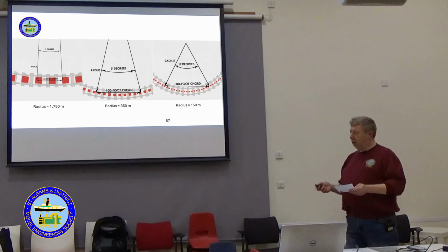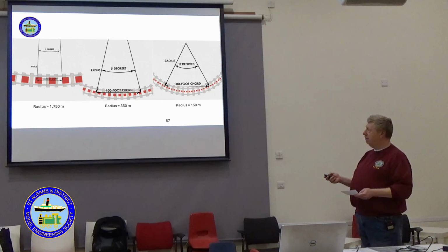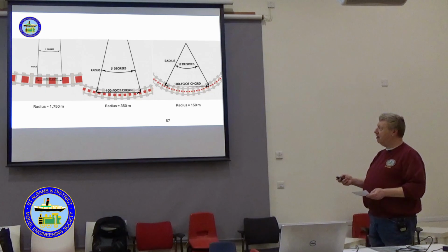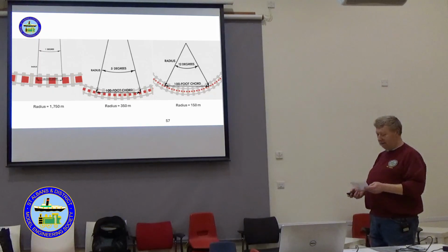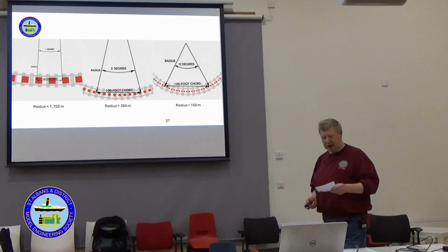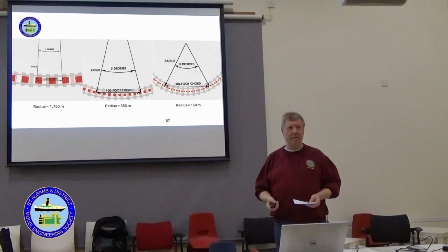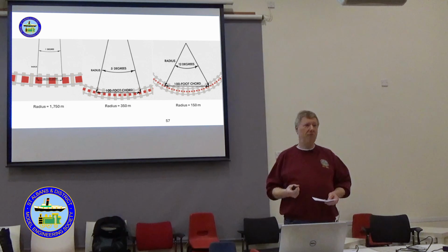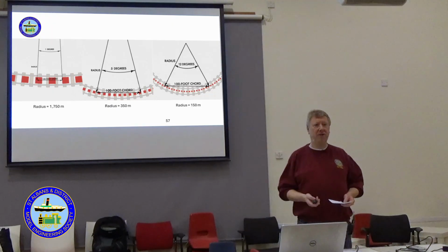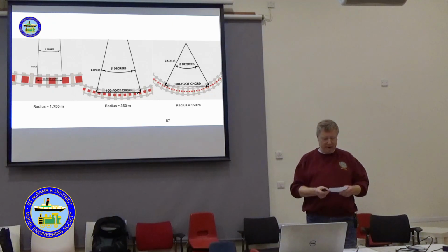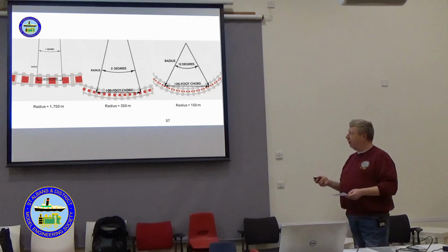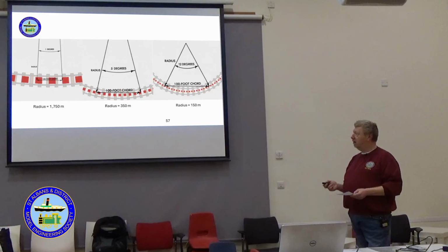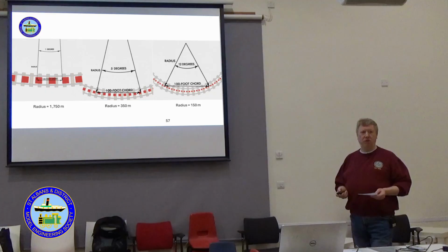For each one of these degrees you increase it, you add half a kilo of resistance for every tonne of the train. So if your train weighs hundreds of tonnes, that's an awful lot of resistance you're adding to it. If you go up to 5 degrees, that resistance quadruples.